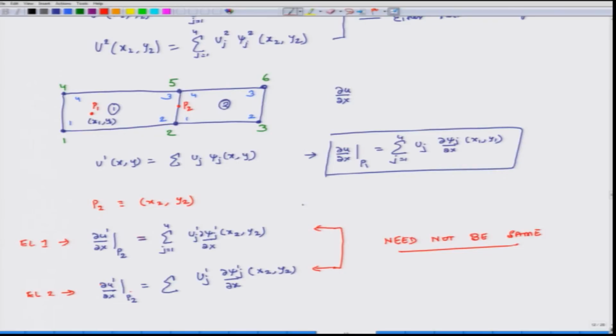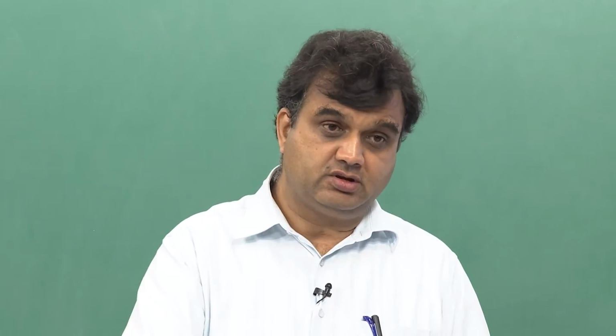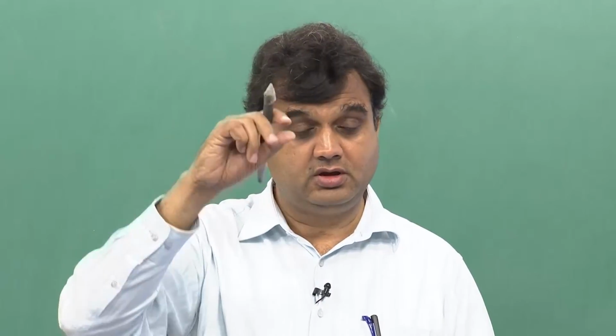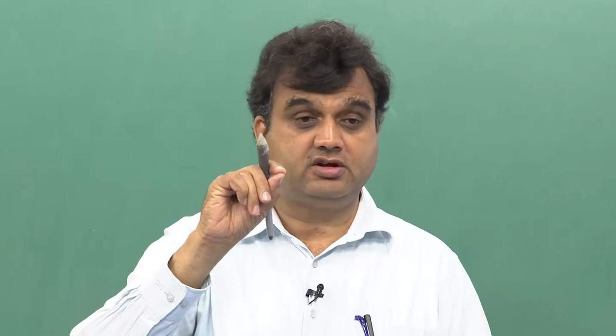See, when we do the beam equation or some other equations, there we specify continuity of derivative also, but in this formulation we never specified continuity of derivative. If we specify continuity of derivative, that also becomes a variable. So, in the beam equation, if you remember, in Euler-Bernoulli beam, each node has how many degrees of freedom?